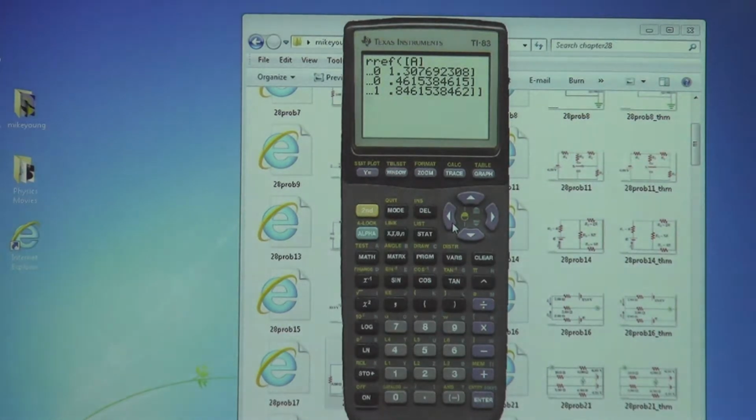Put another way, you don't need to change anything. If you label it one way, get all the way to the end, and say the current I2 is negative 0.4, I'm good with that, because I'll look at that answer and say, okay, negative 0.4, meaning the magnitude's right. Then I'll look up at your diagram for the direction, and negative means opposite of the arrow he has up here, so make sure they match. But I don't care if you go back and change it.